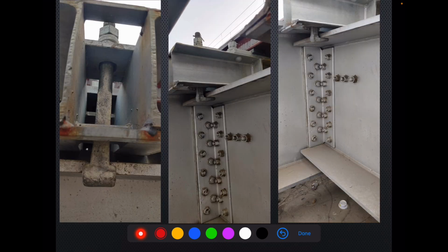Yeah, so this was about a steel channel sleeper, and let's have a closer look at how this holding down bolt goes through the steel channel sleeper and connects with the top flange of the stringer. This is the top flange of the stringer, and these are the channel sections with the help of which the steel channel sleeper has been made.